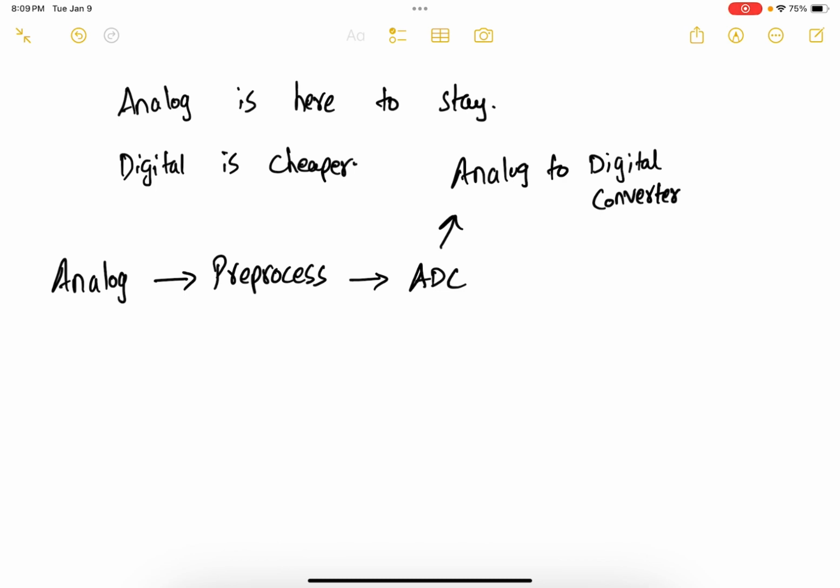So you convert it into a digital signal, then you do some processing. Maybe the signal is coming from a weather satellite, so you are trying to see the weather over the location. So you captured the signal. Now you are using a computer to process the signal, maybe put it on a map or something. And then you use a digital to analog converter or a DAC. Basically, the signal is displayed on the computer screen in terms of light, right? Anything that you see on the computer is basically light intensity variation. So you have to convert it back to analog using a digital to analog converter.